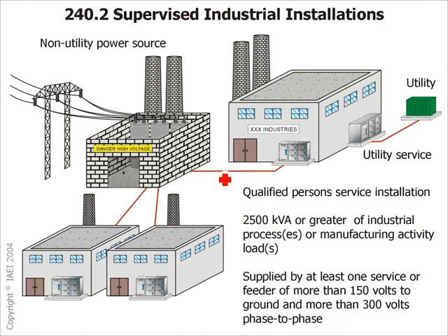That, and qualified people like yourself maintaining the system, then the code relaxes the rules. If you're under these circumstances, but look at the qualified people maintaining the system, 2.5 megavolt-amps size of service coming to it, the voltage is 480/277, then you're looking at relaxing a little bit of rules. They relax the rules in overcurrent protection devices and so forth.